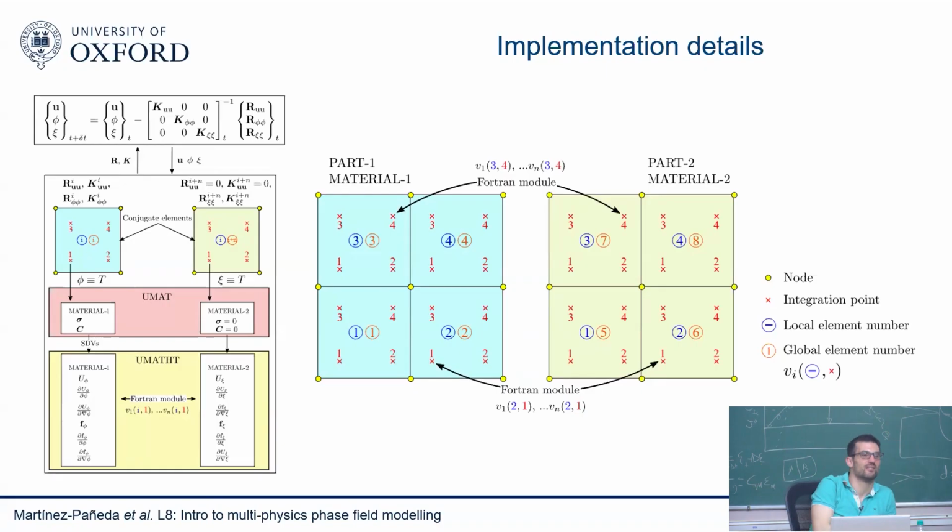Same boundary conditions for part 1 and part 2. In part 1, I will have the boundary conditions related to, again, assuming a small strain, so it's a small displacement formulation, so the geometry will not change. In part 1, I will apply the boundary conditions for displacement and fracture, whatever, if I have. And in part 2 will be the temperature boundary conditions. So you're solving the heat transfer problem in one part, and you're passing around just the variables that you're interested in. Yeah. That's the idea.